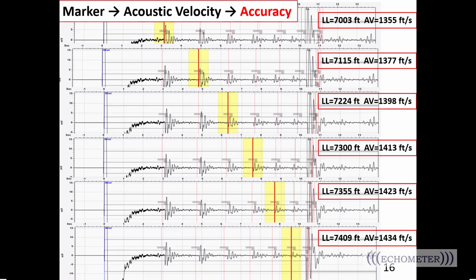it is leaking. Well, that's what the purpose of dual shot was, because on a dual shot you have the casing with the check valve on the outside, and the check valve is supposed to hold the pressure in the casing annulus if there's a packer. And so when the check valve has failed or is not checking, and you shoot a fluid level down the tubing, the pressure wave will pass through the check valve and show up as a signal on the casing.